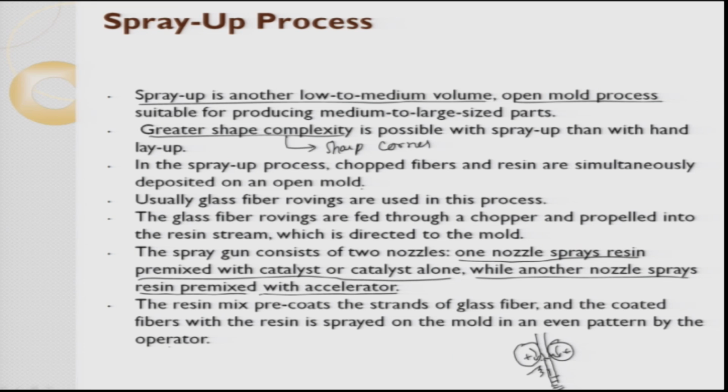If he does not do it uniformly, then at certain patches you will have rich fiber reinforcement and rich resin mix. So it becomes very difficult, and the biggest challenge here is the coating, that means the wettability between the fiber and the matrix has to be done properly. So the interface has to be proper, otherwise the quality of the product is not good.